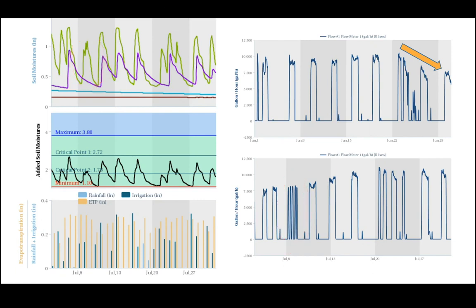So he got that fixed, and we got the flow back up to 165 gallons per minute, and we were back on track. But that was a good example of how I just set that minimum line to send me an email, and we could find a problem in the field through the soil moisture sensors.